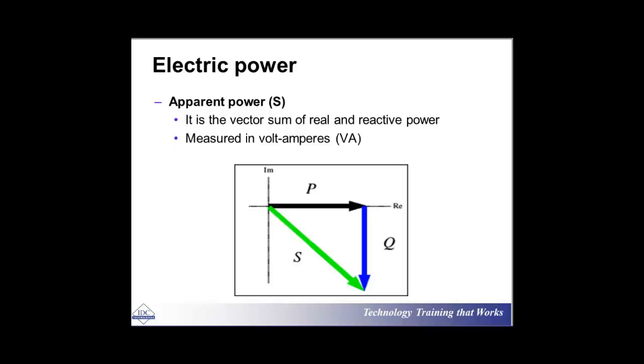You are using P and you are using Q. At the same time, you have got capacitors connected to your load. And again, they will not inject P. P is gone, you have used it. But they will inject Q. So they will make a balance so that the power company is happy.